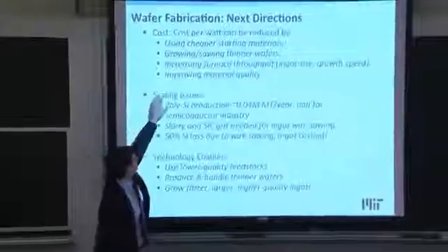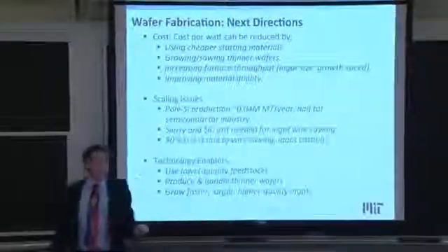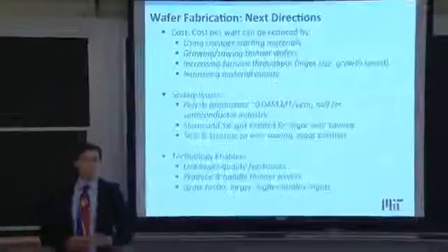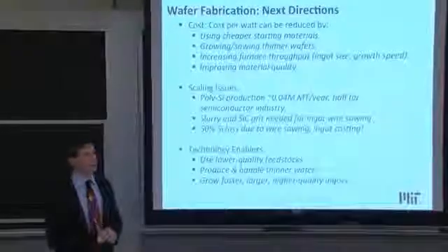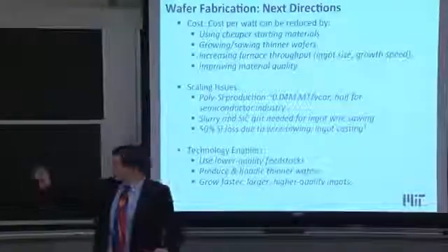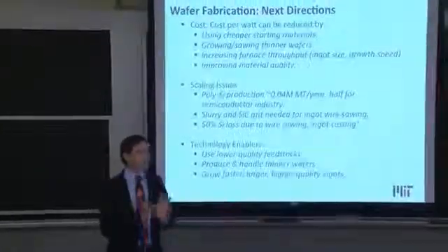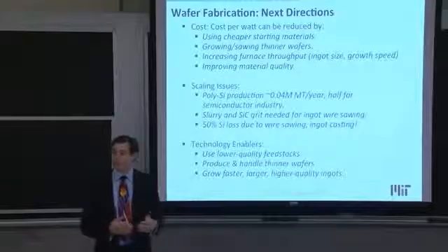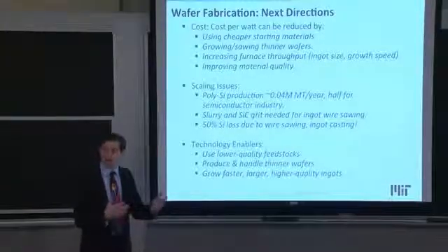And improving the material quality so that you can improve efficiency. Efficiency is a huge leverage over the entire cost structure. Because if your solar cell is able to produce more power, that means you use less encapsulant, less material, and so forth per unit power produced, and even less labor to install it, and less racking and framing materials downstream.